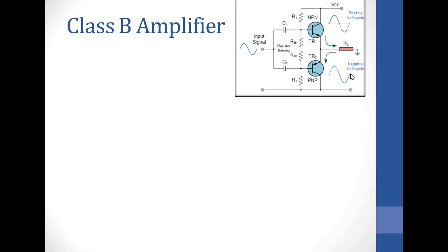So it's actually more like they are helping each other. They are also called push-pull transistors. So once this one is on, this one is off. When this one is off, this one is on. They will exchange. Because of that, it actually means we can double the efficiency. The heat losses will be reduced, meaning that the efficiency can now range between 60% and 70%.